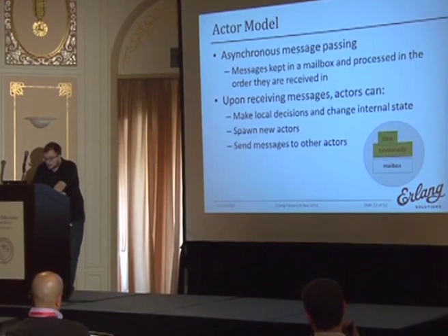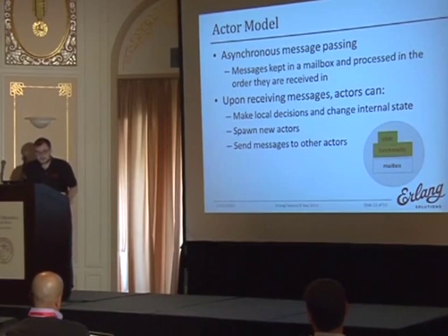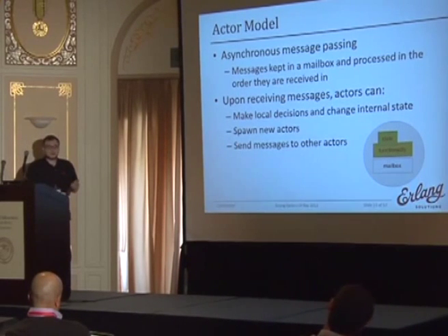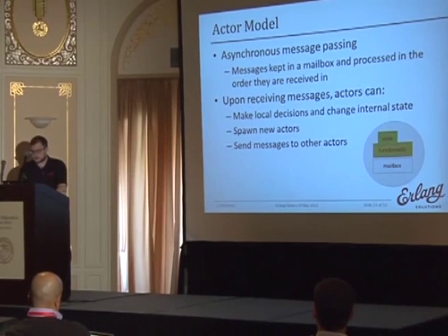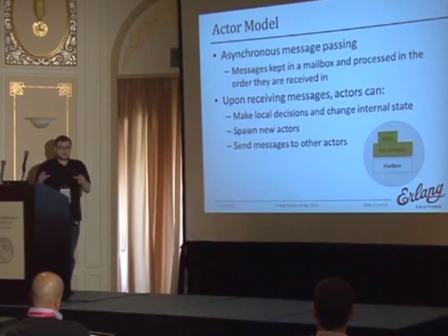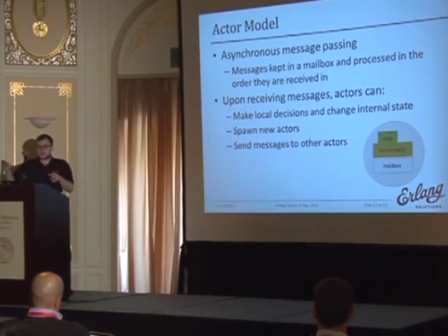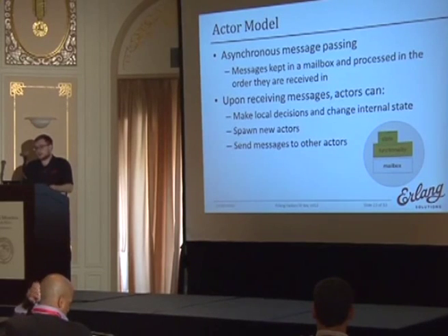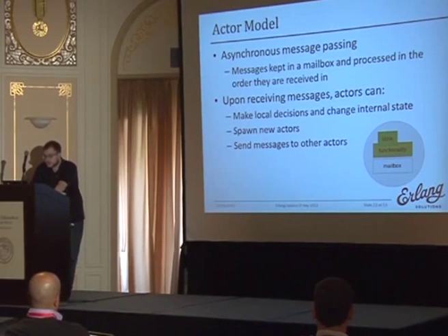We all know about these. They use asynchronous message passing. This is, again, an important feature that can be used in architecting embedded systems, because most peripherals do communicate using some form of serial bus or just a bit-banged interface, etc. And the ability to queue messages in the inbox and then deal with them and do some checks on them is a very useful tool.